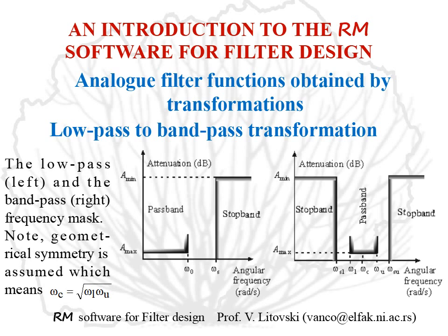As one can see, the values of the maximum passband attenuation and minimum stopband attenuation are retained, while new values of the edges of the transition region are obtained, which are not controlled directly, only indirectly.